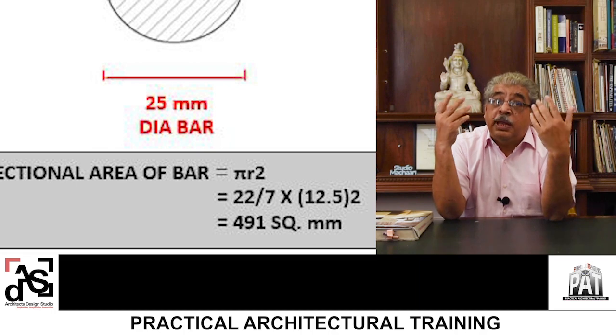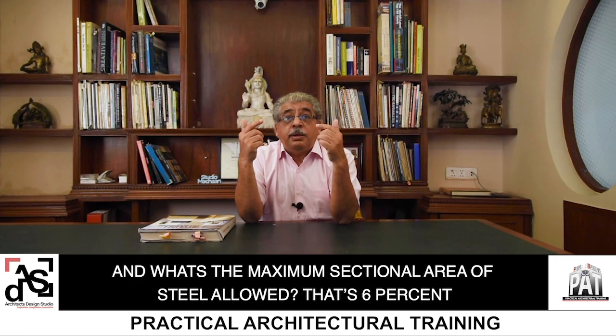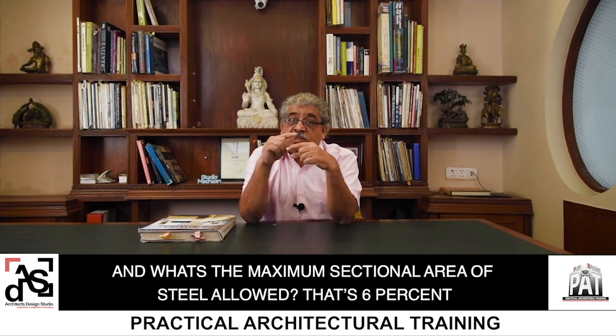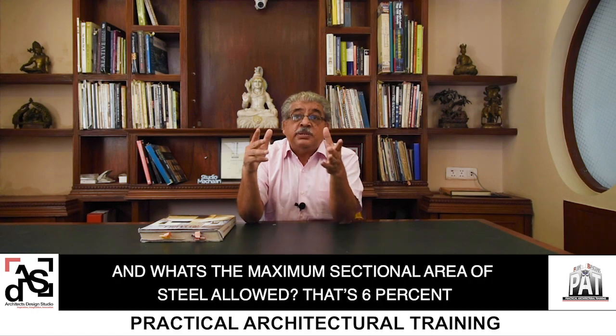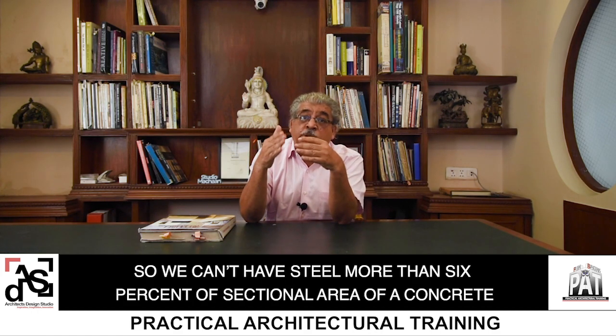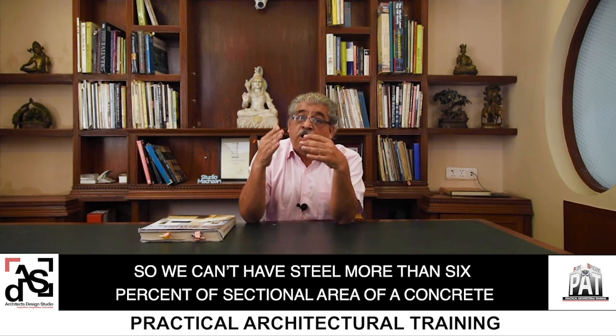So we will need 9 bars. And what's the maximum sectional area of steel allowed at any given section in the column? That is 6%. So we can't have steel more than 6% of sectional area of concrete in any zone.